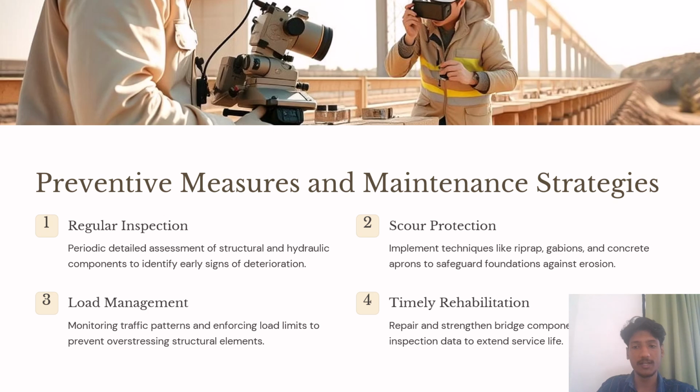Preventive measures and maintenance strategies. First is regular inspection, periodic detailed assessment of structural and hydraulic components to identify early signs of deterioration. Second, scour protection: implementing techniques like riprap, gabions, and concrete aprons to safeguard foundations against erosion.